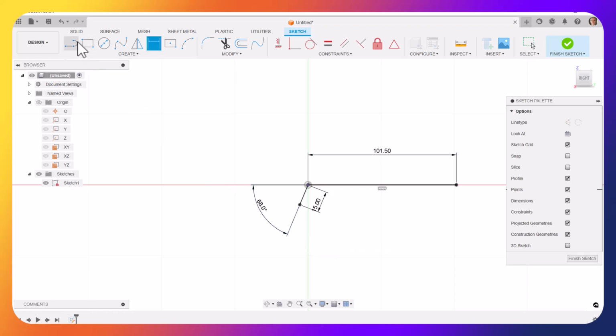And then I'm going to draw another line and I'll put it at an angle about like that, and I'll do my dimension. And oops, I accidentally put an extra line in there. Let me undo that. Okay, now I'll do my dimension, and I'll dimension from this line back to the horizontal line that angle of 30 degrees. And then I'll dimension. Notice there's a white dot on the end of this line, no lock symbol over here on the sketch. I'll dimension the aligned length of that as 42.5, and now everything turns black and I have the lock symbol.